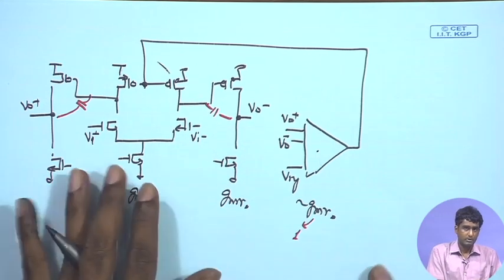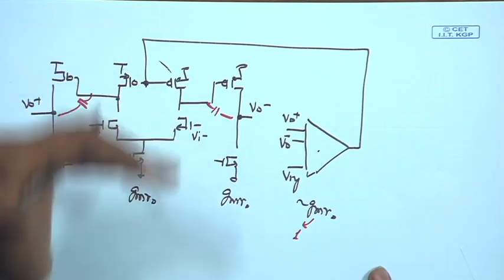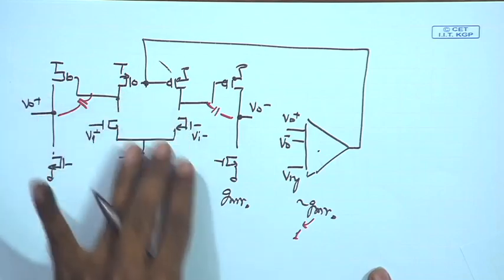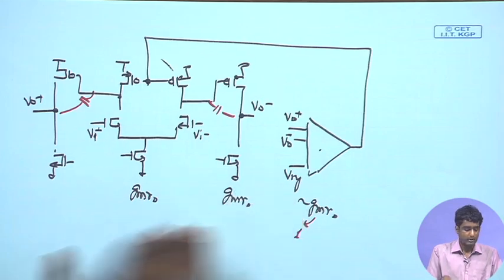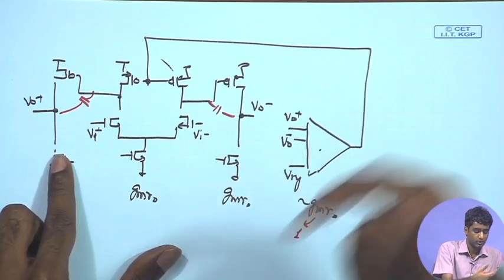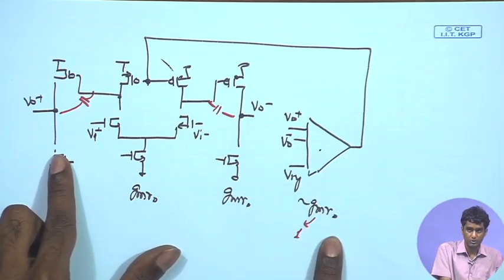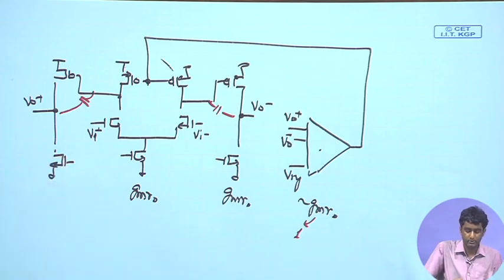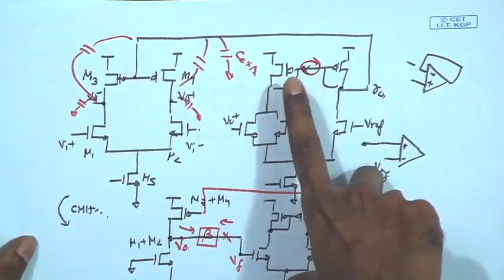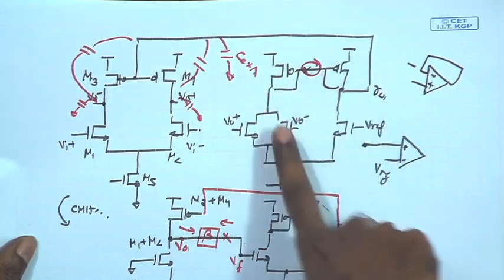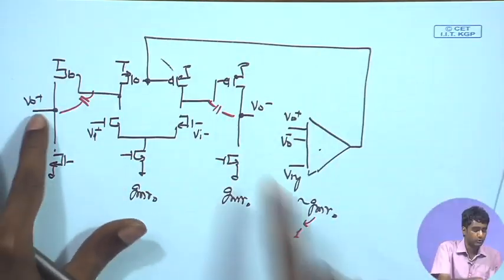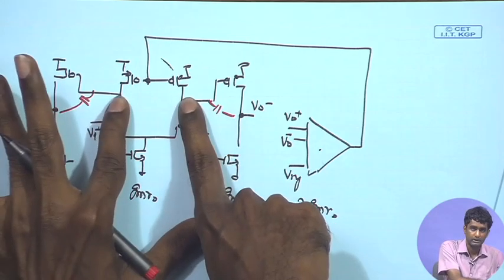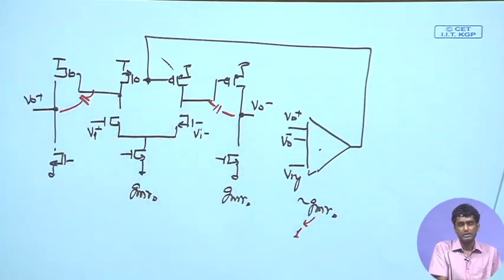However, in the other case, when we are using the common mode feedback for the individual loops, there we will generally like to make sure that the overall loop gain is still large, maybe GMRO square. In that case we will be using the previous scheme, where we have a relatively large gain current mirror load error amplifier, and we will use that loop for the output stage separately and the differential amplifier separately.